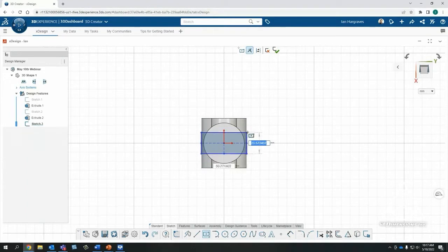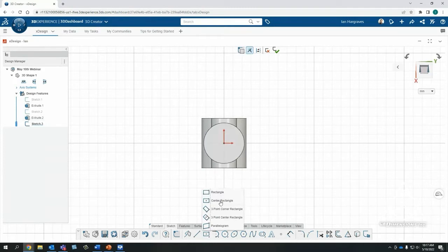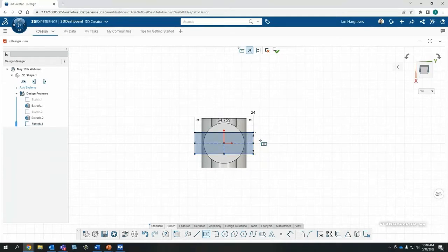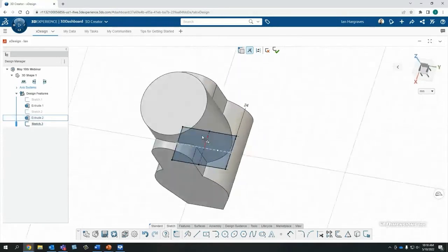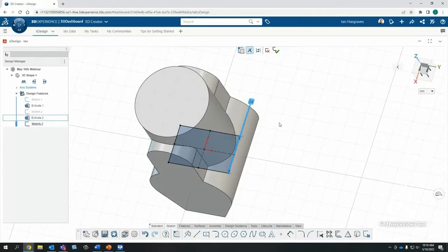So I'm going to use this as, let's see, we're going to do this as a 24. And I'm going to set that to, oops, I exit out of it before. So I'll do 24. And let's, instead of doing a dimension here, I'm going to go ahead and delete that. What I could also do is just a reference here. So I could bring that over and let's choose this guy for a dimension. So I automatically made it as a relation. So again, you can pick relations or you can dimensions, just like we're all used to.